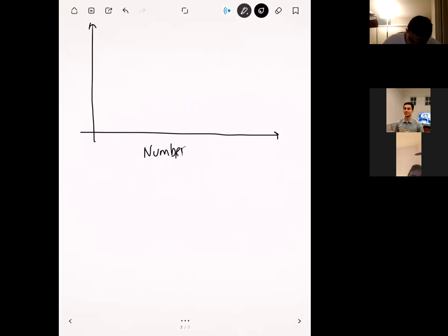All right, and so a good mesh convergence test would probably look something like this, right? You're going to have a scatter plot just like this. On the x-axis, you're going to have the number of elements. Okay, and on the y-axis here, you're going to have the value of a quantity of interest. So it might be the value of stress in a critical area, the maximum stress in your simulation, or the maximum deformation. You know, one key piece of information that you're interested in from the simulation, right?